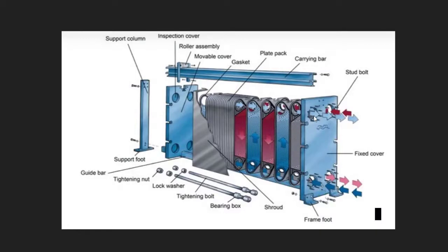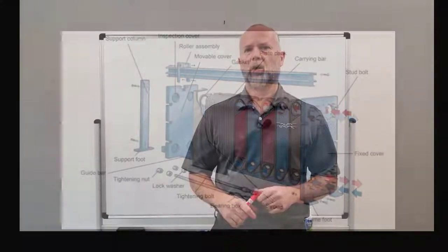Frames can be made of different materials. The most common is painted carbon steel for industrial and HVAC applications, and stainless steel for sanitary applications. Frames are more advanced than they appear. There are strict tolerances to the flatness, thickness, and chemical composition of both the frames and the paint. There are specially cut holes for the tightening bolts and strategically placed feet. Be aware that many companies build frames without these considerations.